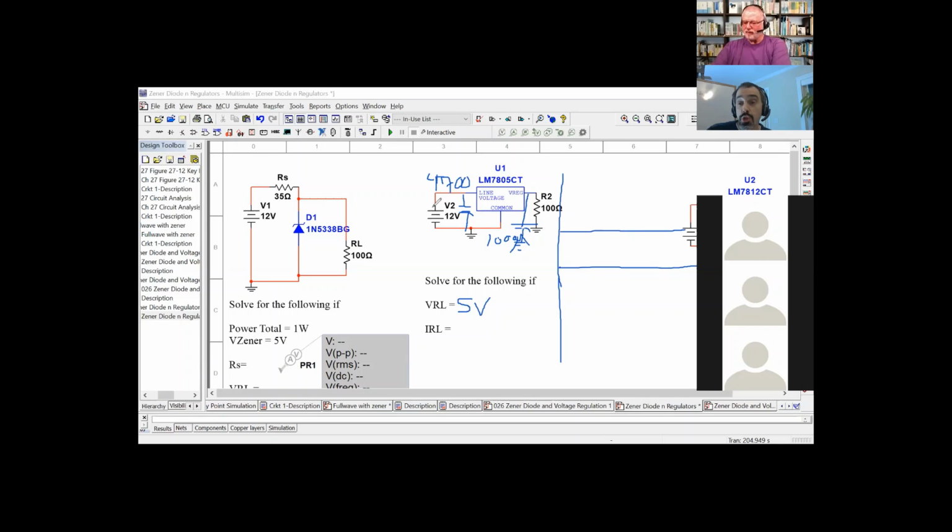So we could have our bridge rectifier come right into this thing, and then we can have this 4700. This could be our bridge right here, right? Then we bring this into the 4700. We may get a little bit of ripple, fine. Hopefully you don't get any. If you do, put another capacitor in parallel. That's not too hard. And then the output right here is connected to the ground, so they're common right here. And this should give us 5 volts.